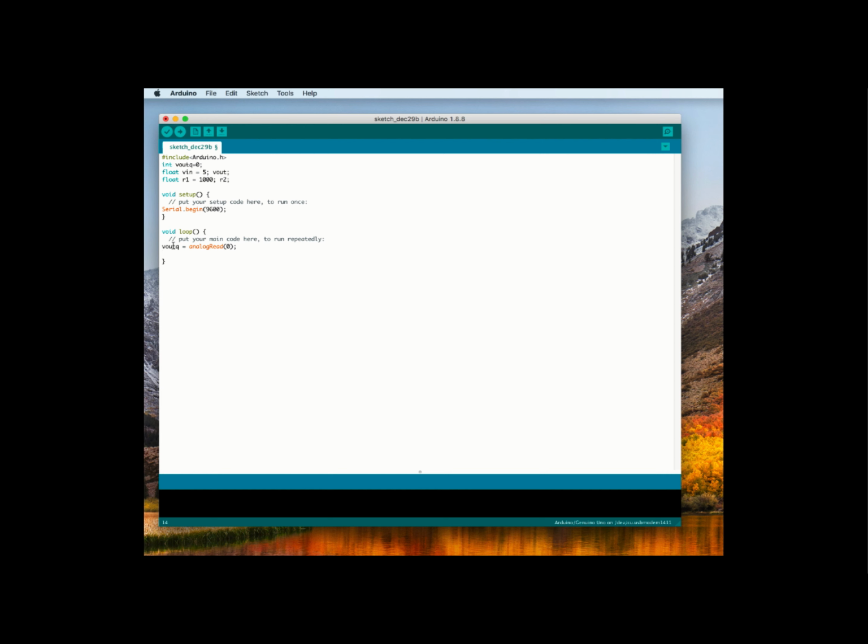So it maps the voltages to numbers, and we need to convert this number back. The conversion is stored in the actual V out. So V out will be V in into V out Q, the quantized value, divided by 1024. So we have got our actual output.